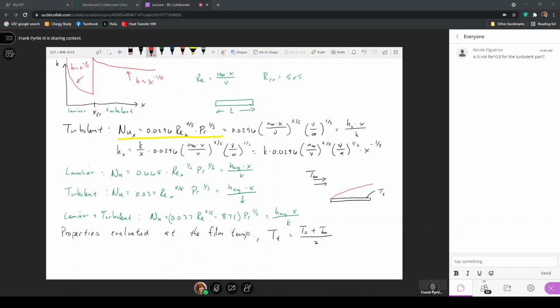And since all the heat transfer actually occurs inside this boundary layer, the film, this is called a film temperature. This thermal boundary layer is viewed as a film because it's very thin, and the film temperature will be defined as just the average temperature between the fluid and the solid surface, because all the fluid inside of that thermal boundary layer is somewhere between Ts and T infinity.